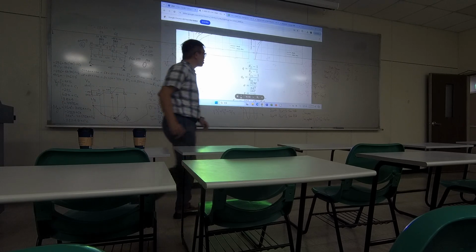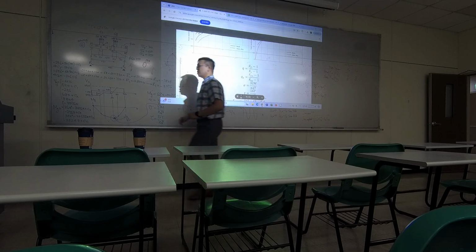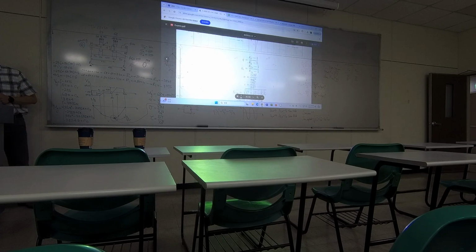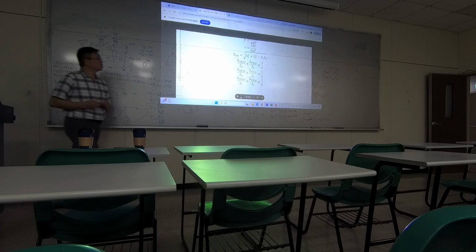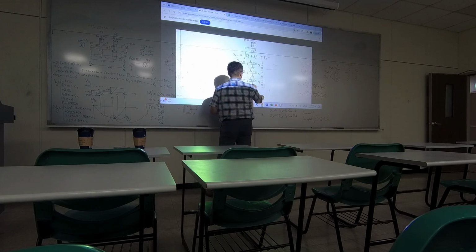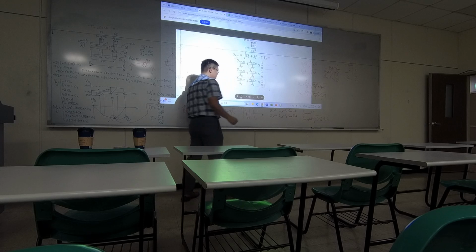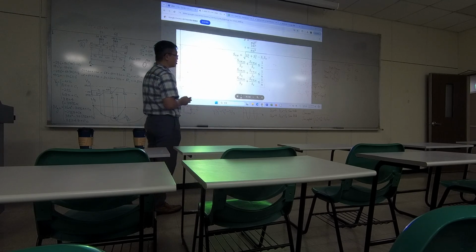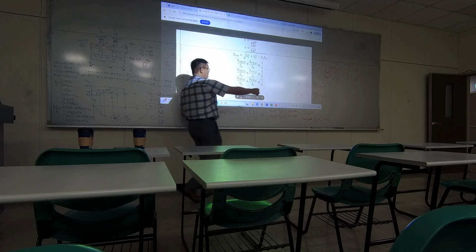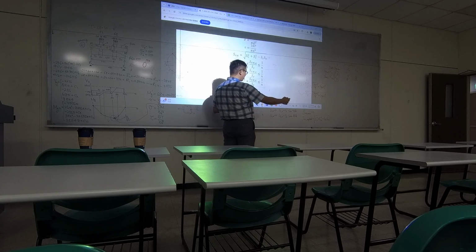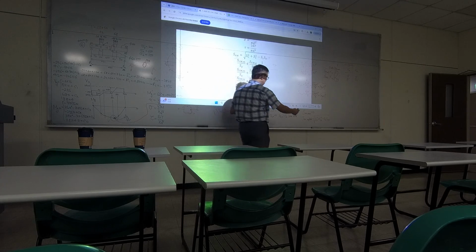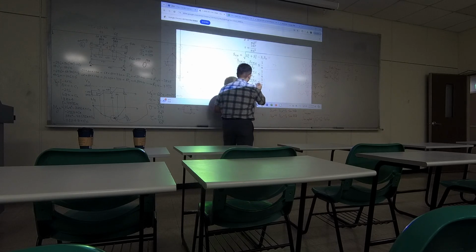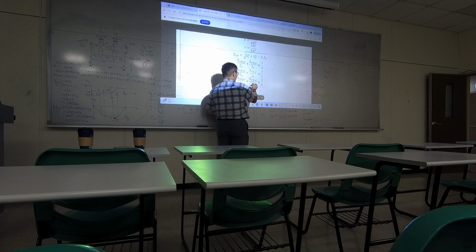Next, when you apply the Soderberg model, which is the one with yield strength and the endurance limit, this is the Soderberg. So when you plug in this equation, actually you don't have a mean part because the mean part is 0. Whatever you get for the von Mises stress amplitude, plug in right here, divided by the endurance limit, smaller than n.